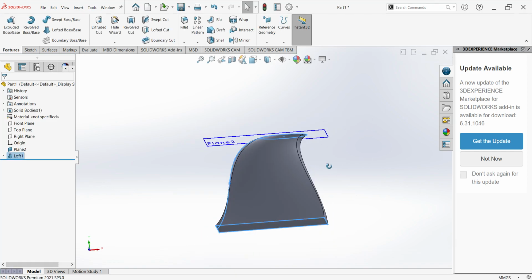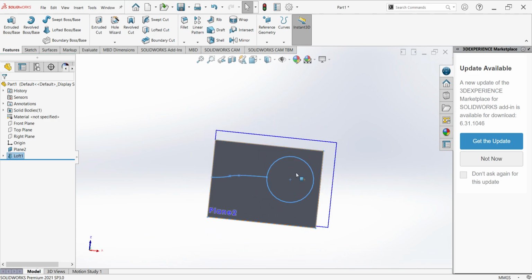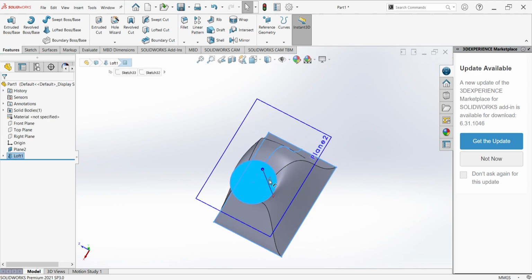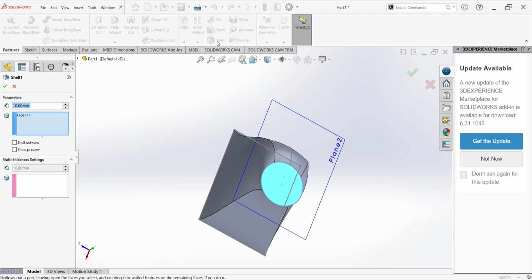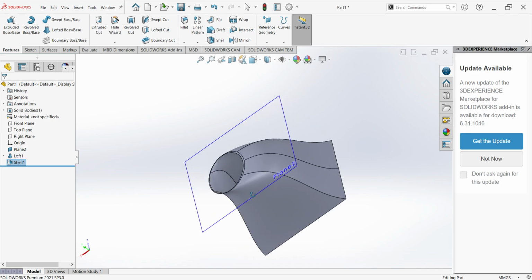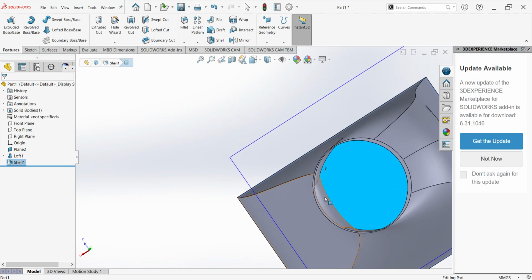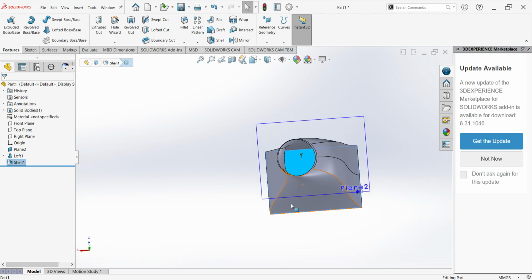Okay, and the sketch is complete. If we want to give it a shell shape, we will use the Shell command. Let's check it out. We have selected it, and we're going to give it some 2 mm thickness. The thickness is greater than the minimum radius, so we're going to give it 0.2 mm thickness, and you can see it has made a shell out of it. It's closed from the other end, but it's a shell inside the shape. It's 3D, but not a solid 3D, it's a shell 3D now.